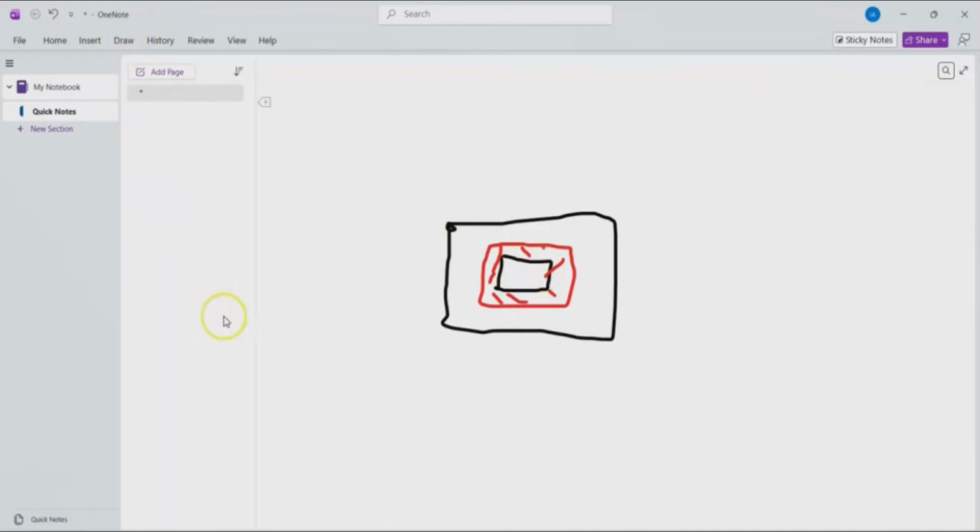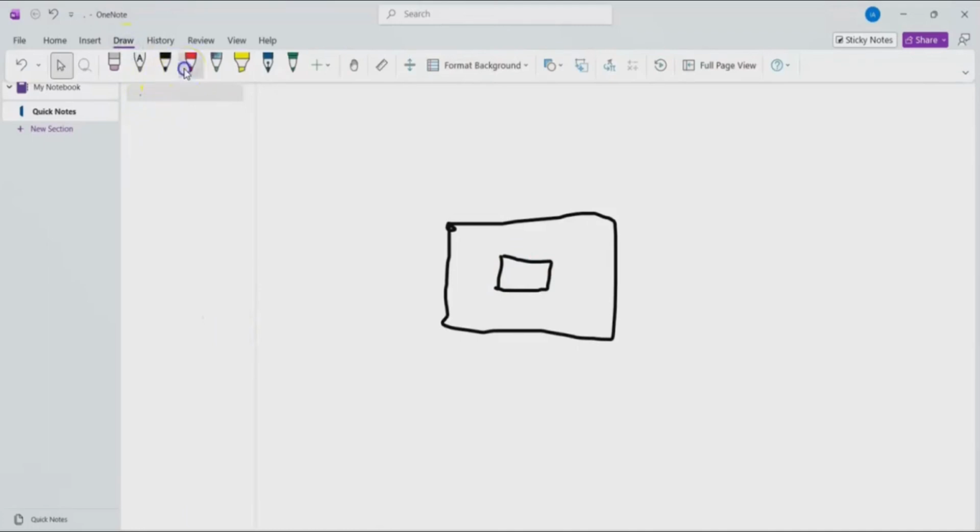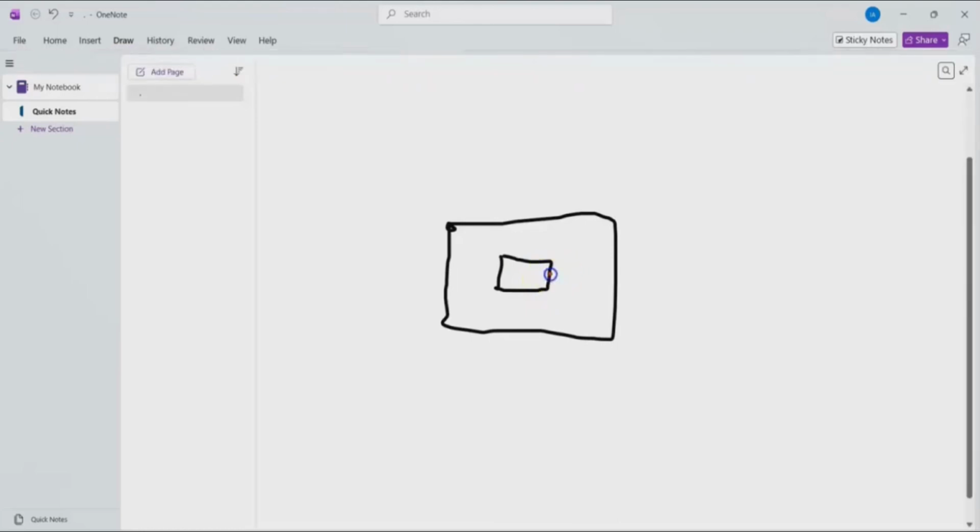Now for the one-way shear, what will be the critical section? For one-way shear, the critical section is going to be at a distance of d away from the face of the column. So d is the effective thickness of your footing. So at the distance of d, at this face, this distance, this whole area is going to be the critical section for our one-way shear.